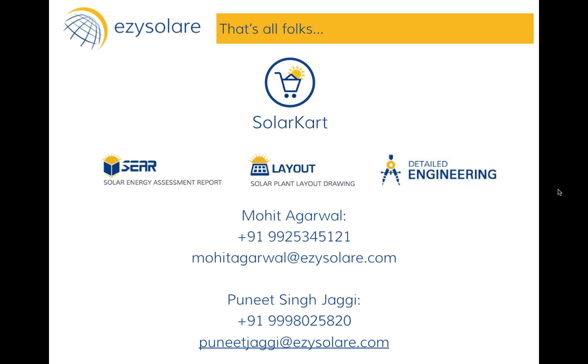Once you have got a positive reading on all of these tests, then after that, the most important test parameter is that of performance ratio, which is the typically agreed parameter. You have got a predetermined period, say a 7 day or a 14 day, or in some cases a 1 month period, wherein you run the performance ratio test. If the plant performs according to the agreed performance ratio, then you consider that plant to be accepted or commissioned.